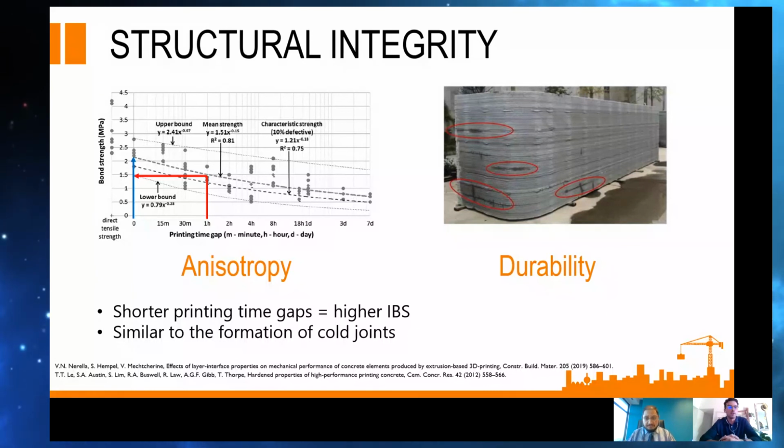Yeah, so we've published a paper on that. It's called Benchmark Structures for 3D Concrete Printing. In this, my colleague Frederick Bester models the fresh state properties of 3D concrete printed filaments and then predicts when these layers would fail. So if you're printing at too high a rate, adding material too fast, then you exceed the capacity of the material in the fresh state, and then you'll have collapse. Similarly, you'll see models from Eindhoven, the Technical University of Eindhoven, abbreviated TUE, where they've got a professor there, Professor SAICE, that has developed models that include both plastic collapse as well as elastic buckling.